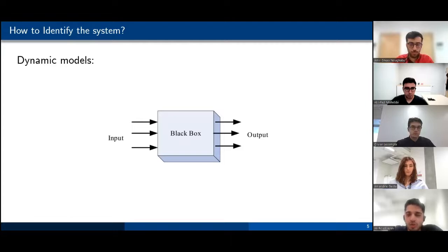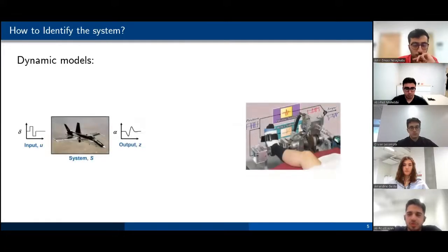So what we do when we face dynamic systems is we use a method such as system identification, which is basically testing the system and giving it different inputs and observing the output, then using this data and some algorithms to understand the input-output relationship or dynamics. For example, when people want to understand how to control fighter jets, although this is a man-made system, in real-world application it's a complicated thing to understand because with time, the characteristics of the system change. So it's always important to have a really accurate understanding of the dynamics.